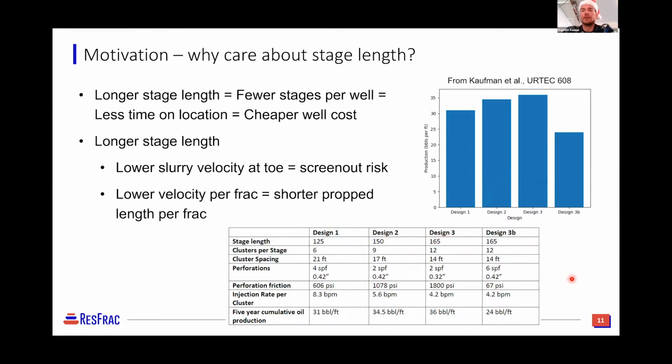And the objective there was to reduce well cost. So when we have a longer stage length, that means for a given lateral length, we have fewer stages, which corresponds to less time on location, which means ultimately a cheaper completion cost.